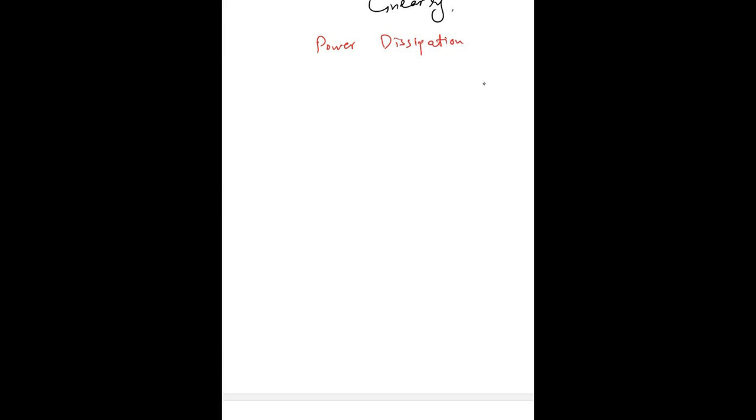But if I write it something like here, I have this CMOS circuit here. This is connected to ground. This is our full circuit, which includes the pull up network and also the pull down network. And the current that flows here is represented by IDD, and here we have VDD. IDD means the current that basically originates from our VDD voltage.